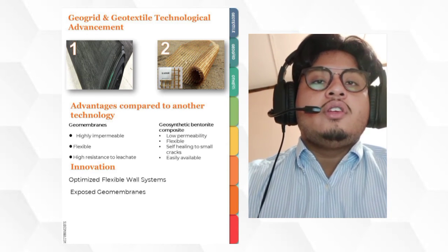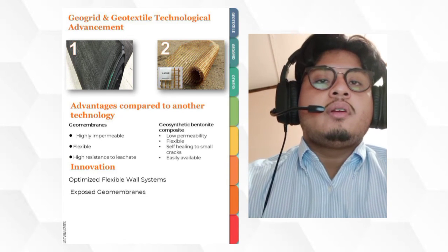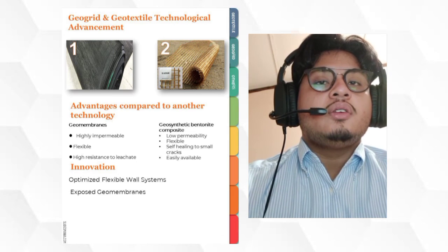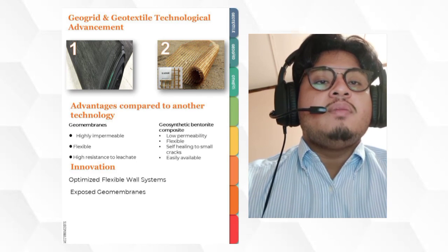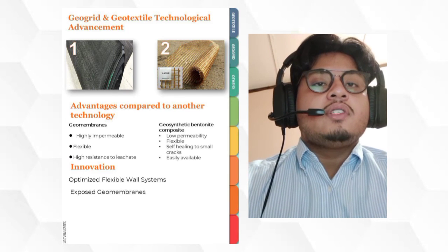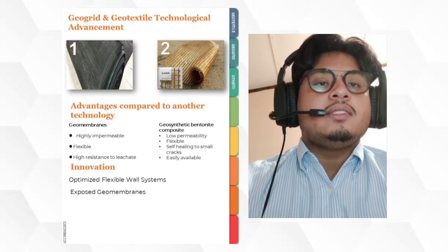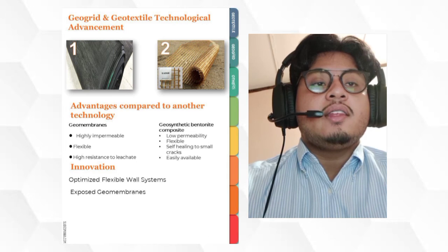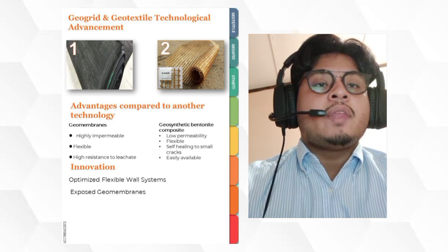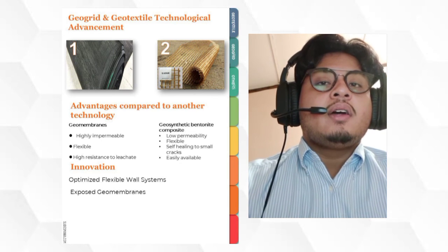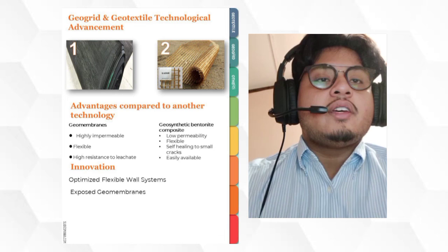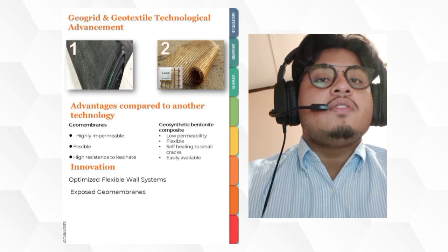The second innovation is exposed geomembranes. Many of the cost and performance related concerns associated with the construction of conventional cover systems can be minimized or eliminated by constructing exposed geomembrane covers. These covers are particularly suitable for sites where the design life of the cover is relatively short, future removal of the cover system may be required, the landfill site slopes are steep, cover soil materials are prohibitively expensive, or where the landfill is expected to be expanded vertically in the future.